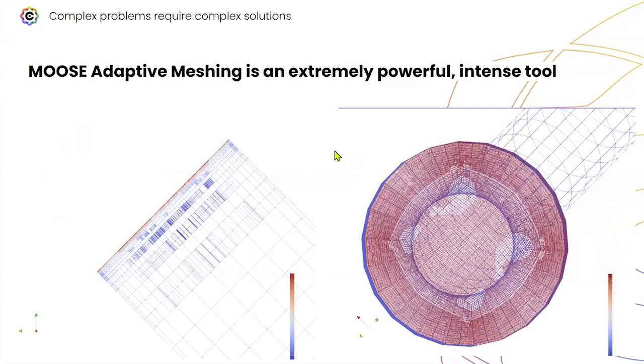For the other one, the similarity of the part to the real world, Coreform Cubit has excellent analysis tools, like analyzing the Jacobian and that sort of thing, to make sure that your description is appropriately accurate. But looking at the MOOSE auto mesher, it's going to look at places where the solution has a high gradient, and it's going to add additional nodes to try to give you more physical solutions and stabilize the answer. And it's great, but it is very intense and very computationally expensive. You can see how the node count can increase quite dramatically here.